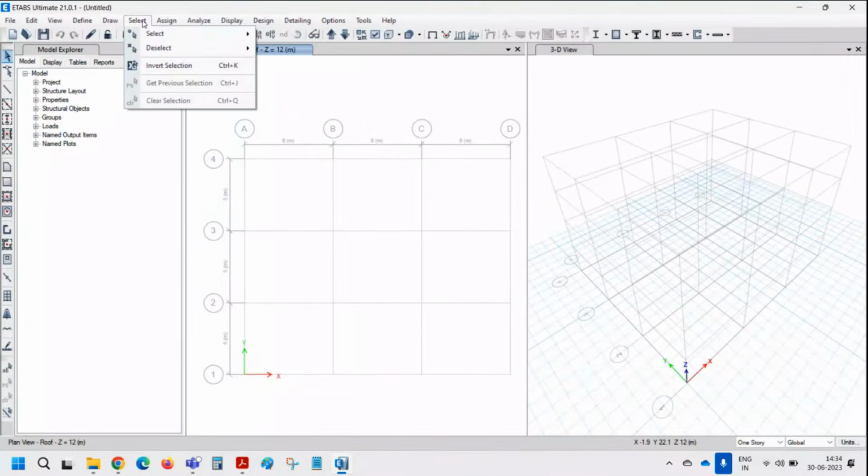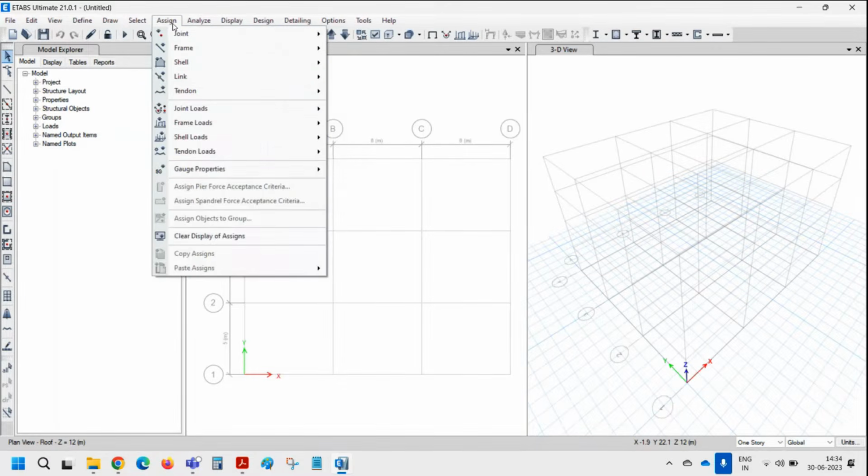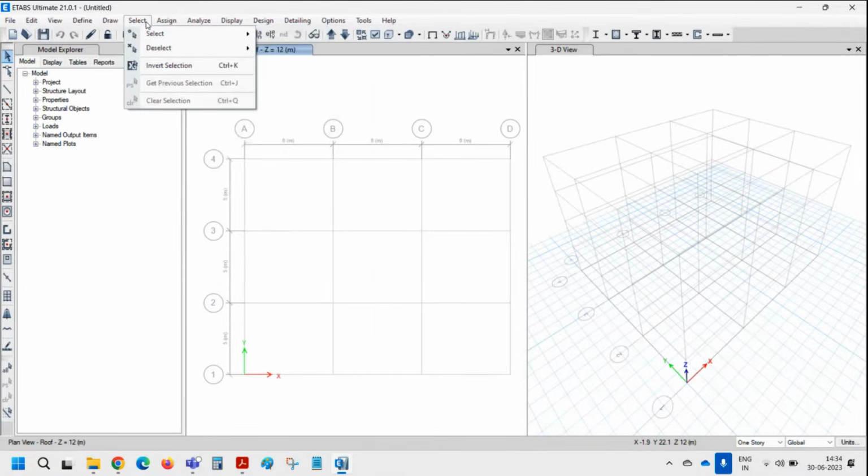For example, you want to select a beam and apply a load, a floor slab load, or change its properties, or apply different assignments, property related. Then all of them will happen with this. You'll select something and assign something. So you'll combinedly use this. So with that, your modeling assignments such as loads, properties, changes, or frame releases, numerous things that you can work with in the modeling, we'll complete everything with this.